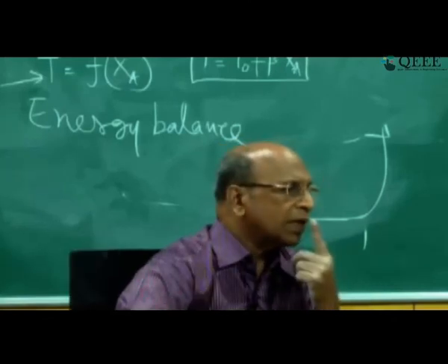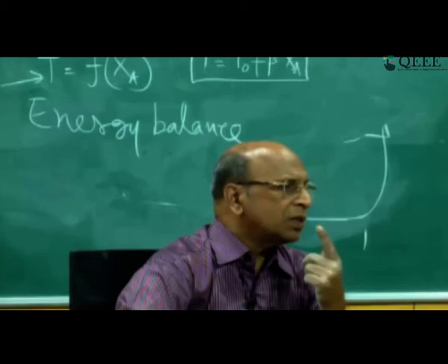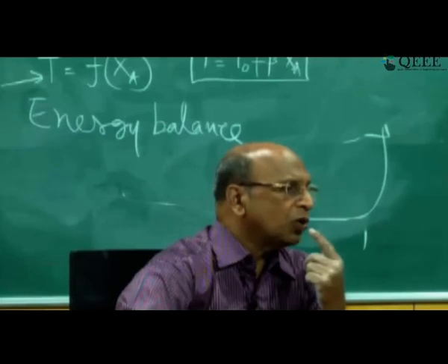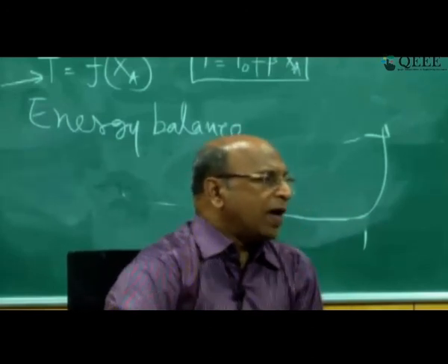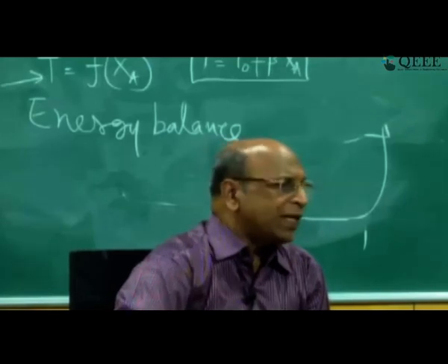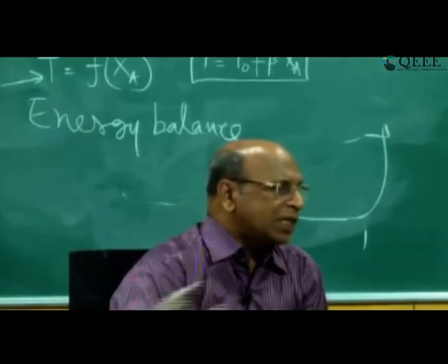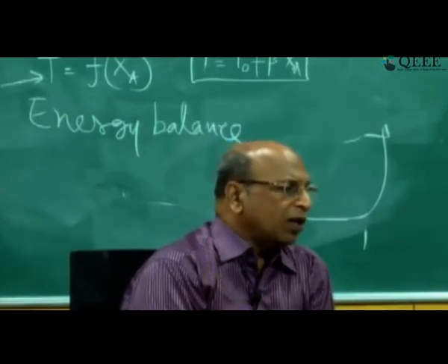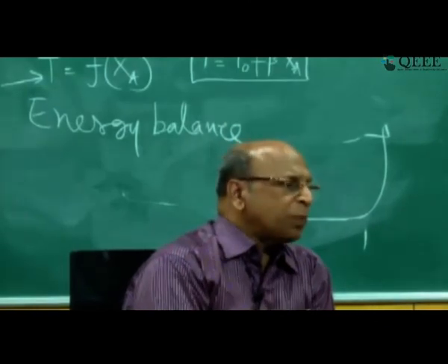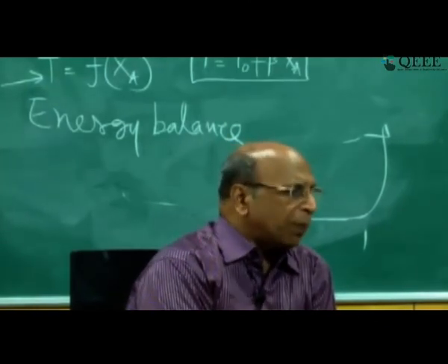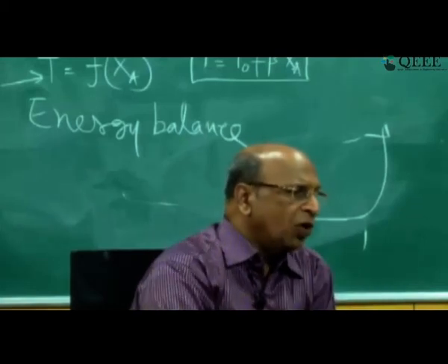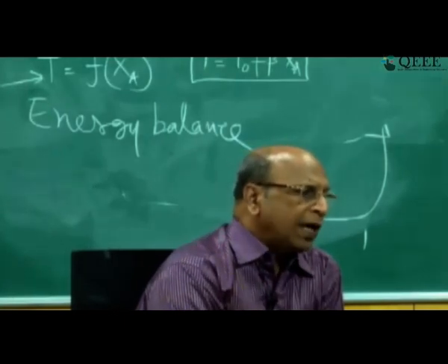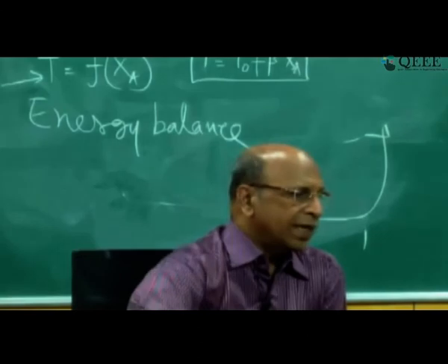Other questions? Sridhar sir. For a variable volume system, which reactor can be used to get better efficiency? For variable also, plug flow is the better, provided it satisfies all other conditions like small residence times and all that. Either for variable or constant, all the particles will spend exactly the same time. So plug flow is the better for n greater than 0 all the time. That's not a problem at all if you want to use plug flow and then see its limitations.